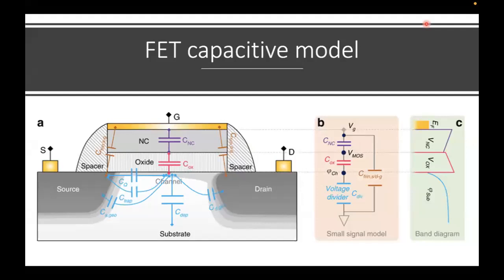However, this is not the only reason for having capacitors. For example, having a p-n junction is another reason for having a capacitance, because as you know, a p-n junction includes in between what we can call the depletion region, which is an indirect form for a region depleted from carriers, or between quotation marks, an insulator. So p-n junctions are another source for a capacitance.